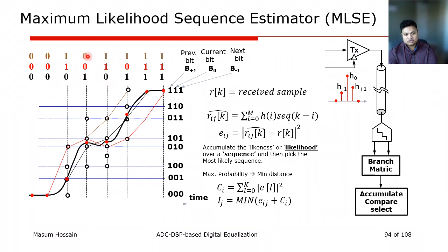Each of these possibilities is indicated with the lines in the graphical picture. As we see, when we extend our observation horizon beyond this symbol point, the brown line deviates from what actually took place, and the red one also deviates further away from this black line, indicating that in the overall picture these two are less likely to happen, and the only survivor is the black one.